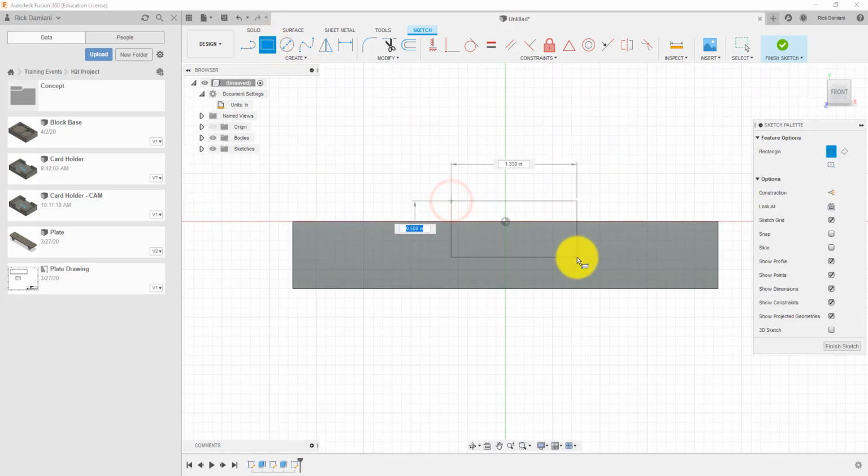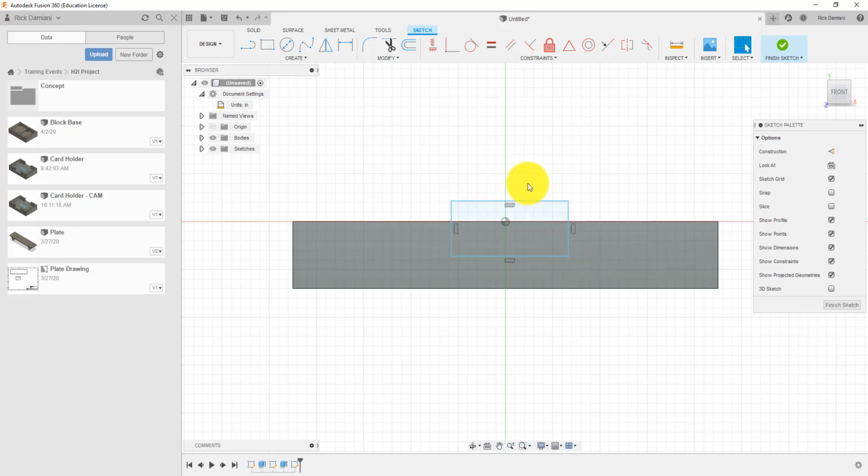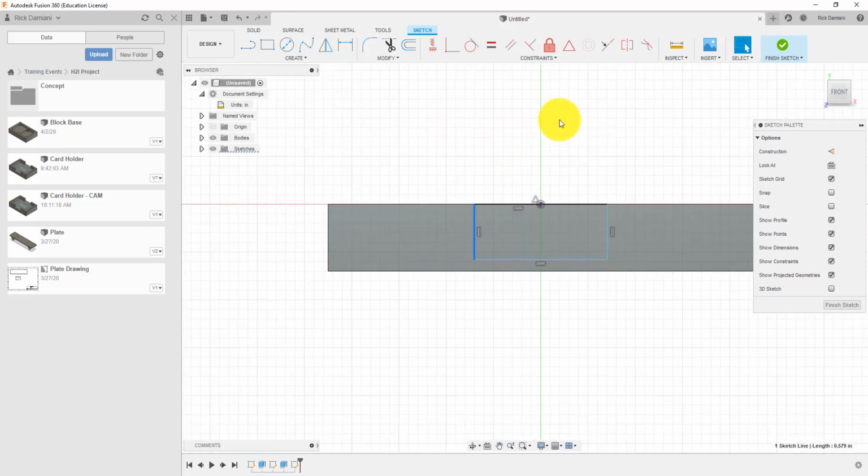I'm going to intentionally create this a little out of position because I want to create a rule between the origin, hold down the shift key, and this line. It's difficult to do if they're on top of each other. I want to use a midpoint rule on those lines. I'm going to escape to stop creating rules. And a midpoint rule allows that to happen. That line is locked into place, and this shape is locked onto the center there. That's perfect for me. Right?